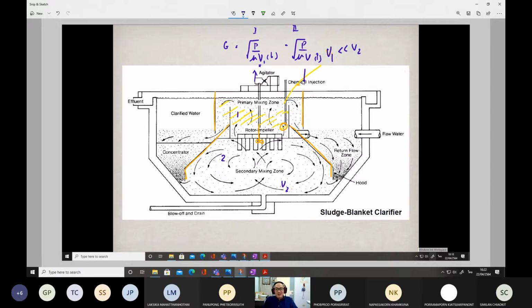Once the chemicals reach all the particles and the particles are completely mixed, flocs are formed in the lower compartment. As water always gets into this chamber at the center of the tank, some of the water must lift from the inner compartment to the outer compartment.